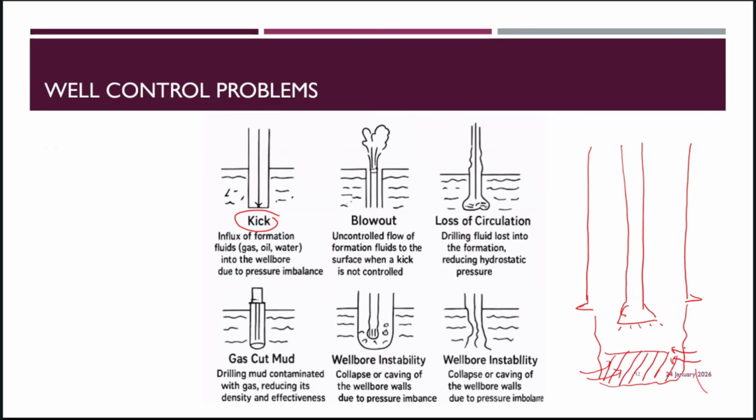Mainly it is gas. Gas from the formation penetrates our wellbore. This is called a kick. By definition, it is an influx of formation fluid. It can be gas, oil, or water in the wellbore.